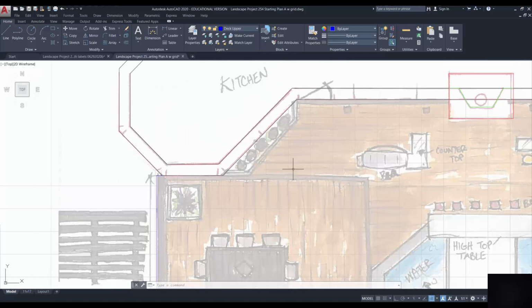Now to pick up this line, I have a choice. I can pick up the end of the building, or I can pick up the end of the line. I'm looking at how it is more easily defined by the existing structure, because I have to dimension all this. So instead, rather than pick up the end of the line, I'm going to go right to the end of the building, and I'm going to go across this way. And that's an easier number for me to pick up. And the numbers are somewhere around that 13 foot mark. Okay, so we'll type in 13 feet, comma 0.